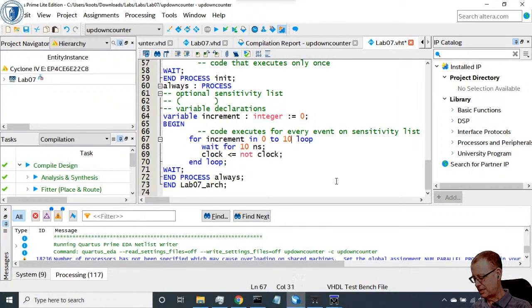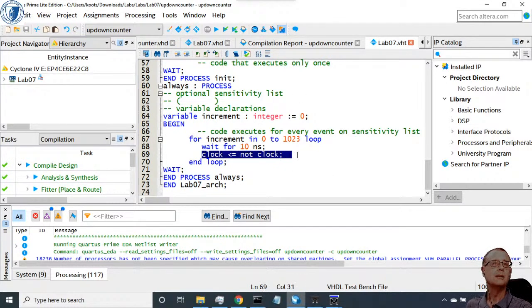If I want to see whether the counter loops back to 0 and keeps going, I need to make the number of toggles 1024 rather than 512. If the number of toggles is 512, I only get 256 full clock cycles, right?